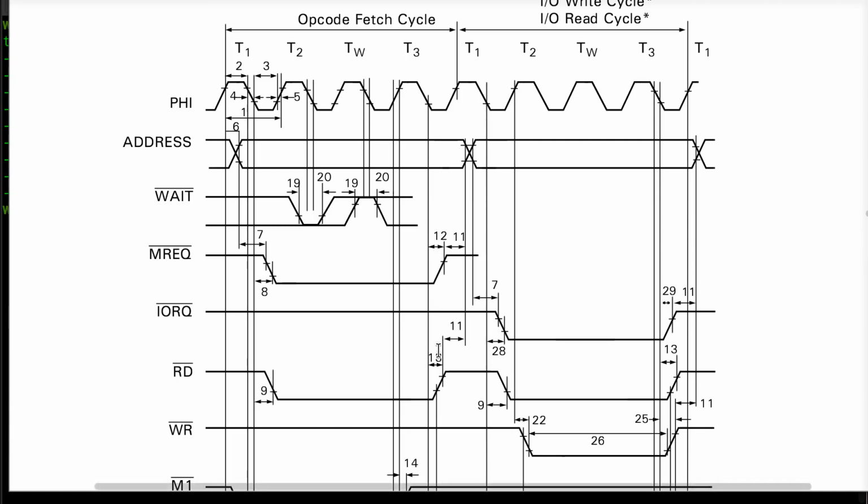If you look at these up in the timing tables, the 12 and the 13, these are 25 nanos each, which means that this could go high along with the rising edge of T1 in the worst case. Over here, you've got 8 and 9 from the falling edge of T1, showing that these will go low no later than however long these timing constraint numbers are from the falling edge of T1.